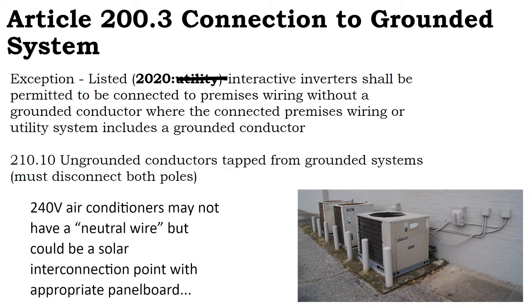What does that mean? Okay, well, not all 240 volt electrical devices have a neutral. The neutral is kind of there for imbalanced loads, but 240 volt devices made up by 120 split legs will function without that neutral path, provided that the load is perfectly balanced. I don't want to get into what all of that means. I just want to kind of cheat and tell you that some air conditioning units don't have a neutral.